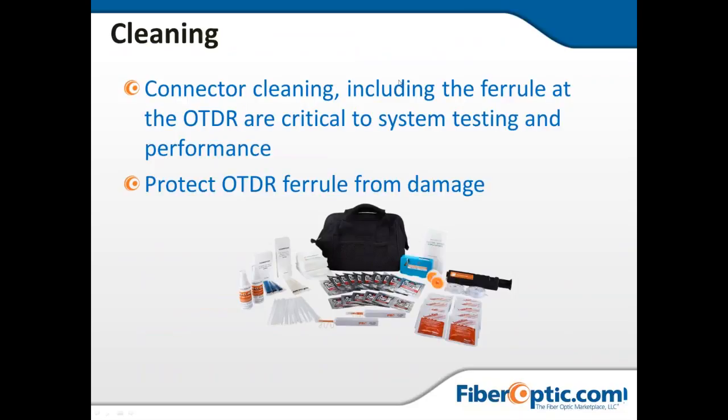Connector cleaning should be relatively simple. All you need is some alcohol. These cleaning sticks down here, the CS125 and the CS-250 work really well. You just take the cap off, stick it in there. It does a wipe of the end face of the ferrule and cleans all that debris and takes it out.